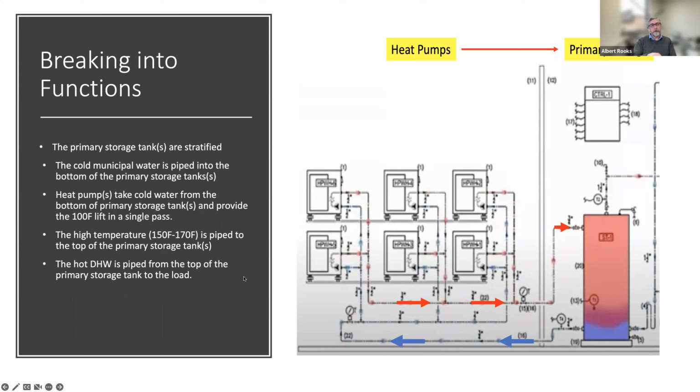At some point, we run that circuit and we've taken all of the water out of that primary tank, imagining that primary tank is cold. This is startup, day one. The whole tank is blue because it's cold. We run that circuit and we start pushing that 150-degree water into the top of the tank. And essentially what that does is start pushing that cold water all the way down, and it keeps pushing it down until it gets to the very bottom.